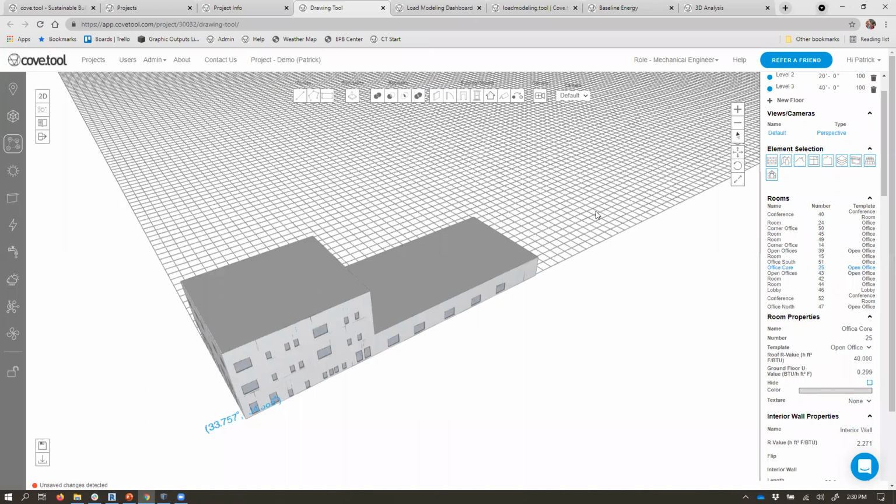Because what will happen is we're actually going to take the area weighted average of this roof plus this roof and pass that to the baseline, that super quick energy model. And that's some of the calibration that we're doing. If I put in that detailed information to do my loads, because I have to do my loads, but I really wasn't interested in energy, we're going to pass it to the energy anyway, so we can see the impact and we can know a bit more about our building.